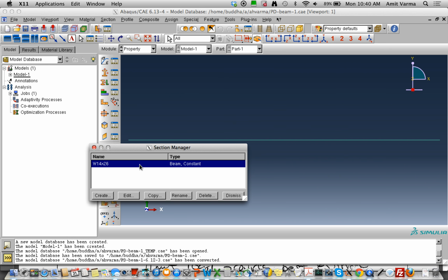And you can also put in a generalized cross-section. In a generalized cross-section, you don't put in any dimensions. You directly give it the moment of inertia Ixx, Iyy, and you give it some of the parameters that it needs in order to be able to define it. So you actually don't give a shape. You directly give it the cross-sectional properties. So in this case, we selected an I shape.